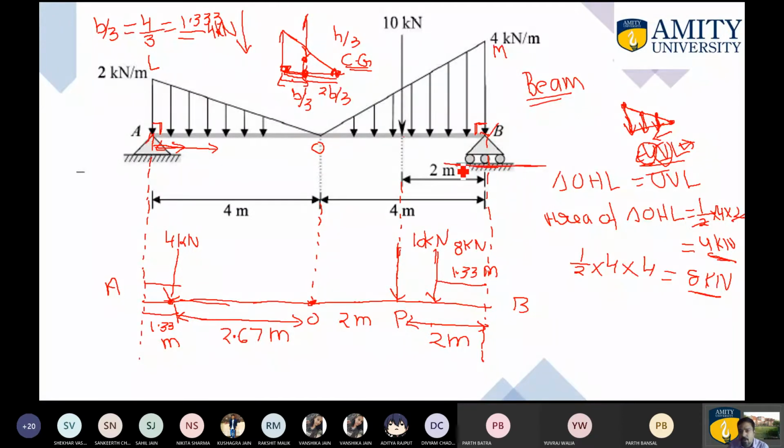So the roller is moving on this horizontal surface, so a reaction will get generated, which will be vertical. This reaction you are required to calculate. It will be represented by RBY, the reaction at B in the Y direction. Now focus on this one.